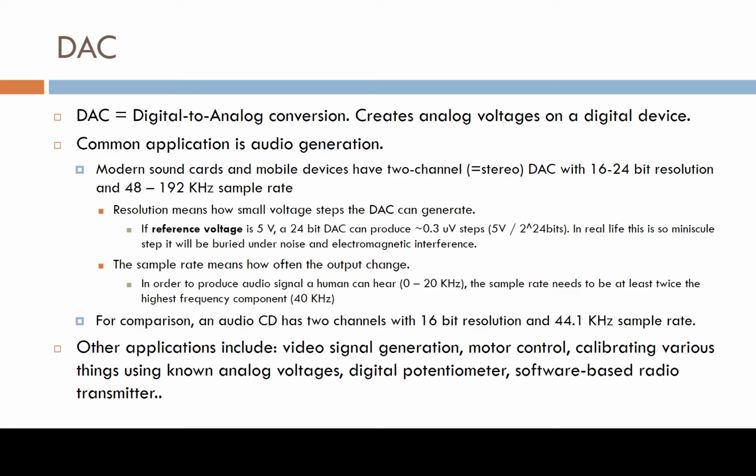The resolution there, 16 to 24-bit resolution, what does it actually mean? Well, that means how small voltage changes the DAC can generate.